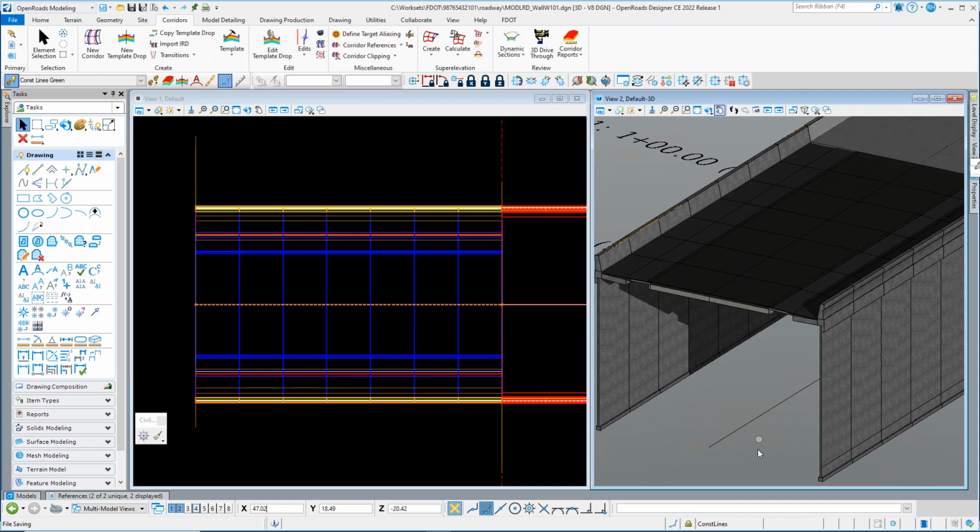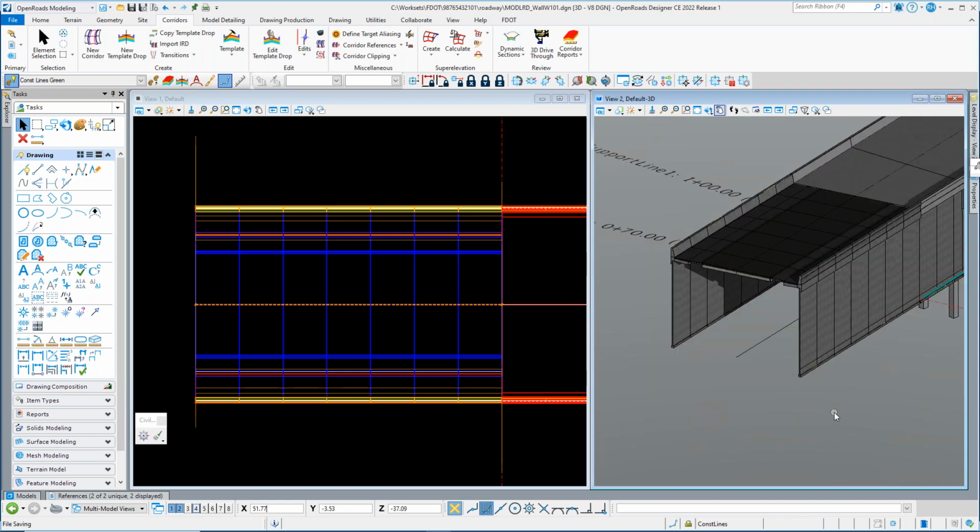We've got enough time. We're going to go through and create some geometry, some mostly vertical geometry, to act as a target for this MSE wall leveling pad. And there are numerous ways to do this. We can actually go through and create geometry and sketch out a profile on it. But in this case, our structures folks were kind enough to give us a text file that we're going to use, and we're going to import geometry from that.